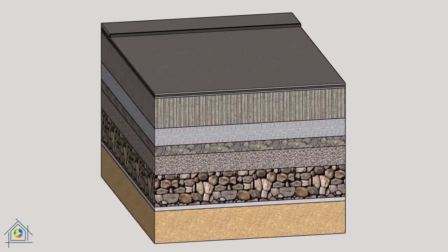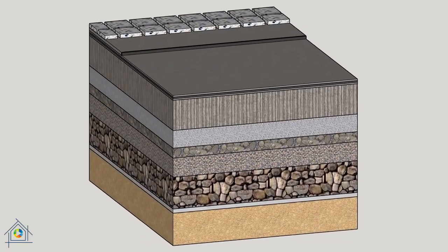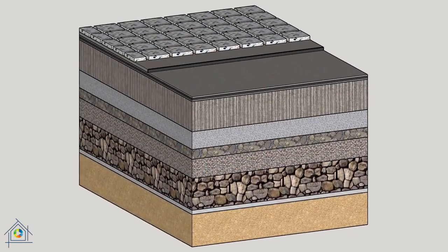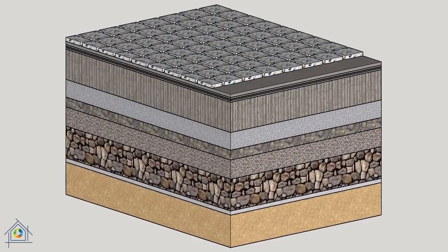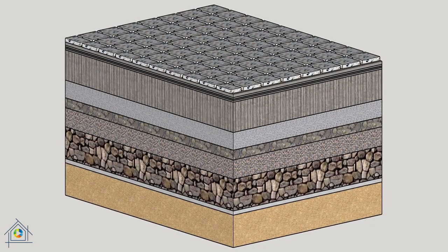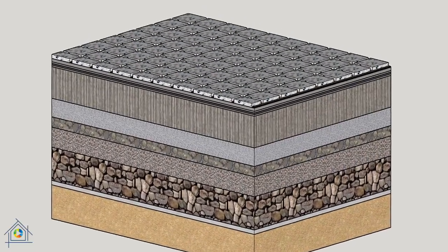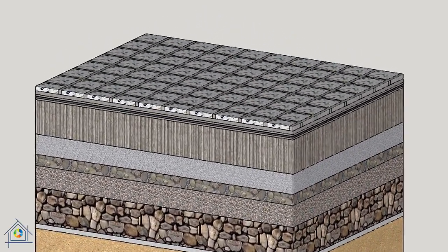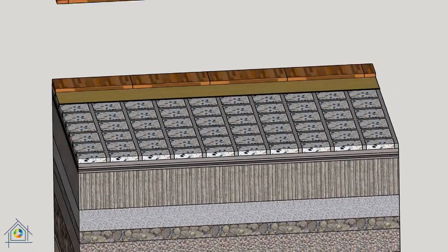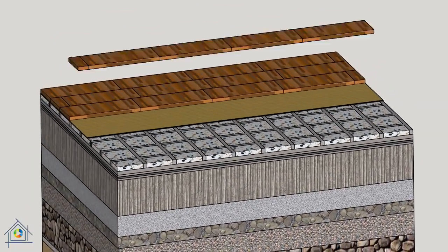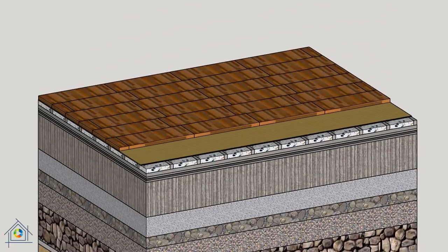The cement terrazzo is attached to the underlying layer using a cement sand mortar with at least 200 kg of cement and at least 2.5 cm thick. The thickness of the cement terrazzo is at least 2.5 cm to withstand loads and ensure proper durability. The gap between the cement terrazzo is filled with cement grout. Finally, the parquet pieces are laid on the cement terrazzo surface with special adhesive.